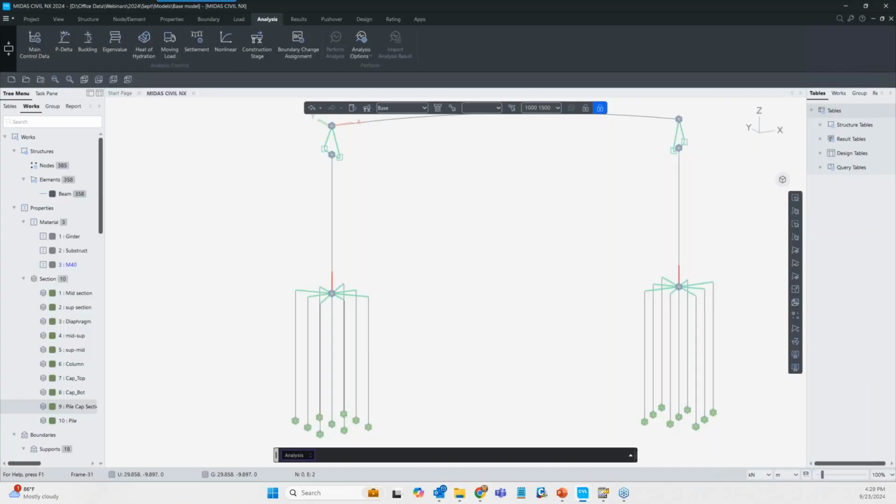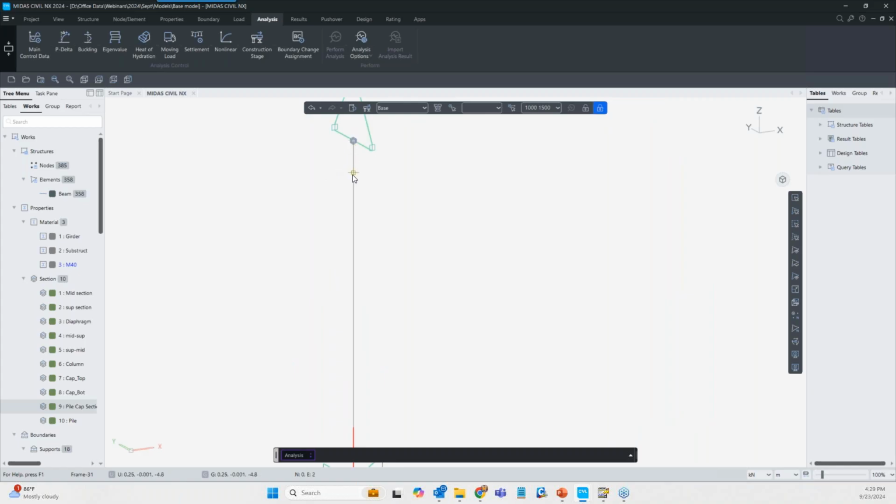How to manually model flare sections without the plugin? See, the flare structure which is created is basically a tapered section. If you want, there are different ways. Either we can create just a single line element, and through that you can have multiple sections in the tapered part. So here, if you check the column top and column bottom, they have different properties.